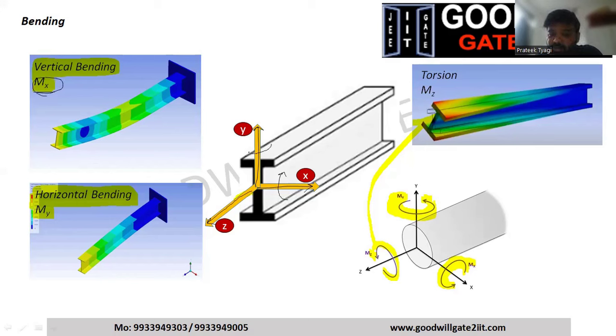I have a moment which is rolling about the y-axis, which is My. So you will not see any Mz in bending. Mz, which is moment about the z-axis, which will try to twist my system, will come in torsion. So as of now, we don't have any Mz. We will only focus on bending, which is Mx and My. So I just need a quick nod.